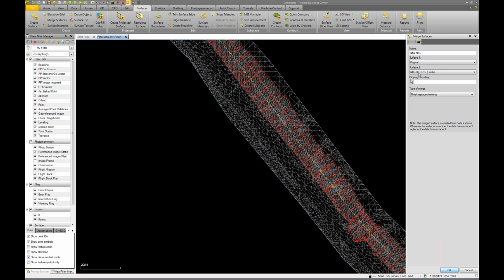So that'll replace that surface anywhere that exists. And then my final surface name, I called it after northbound lane. So now I'm going to have basically an intermediate surface in my construction. And I'm going to use this to target my southbound lane. And we'll give it another 10 or 15 seconds here to complete the merge operation. It should show up here shortly.